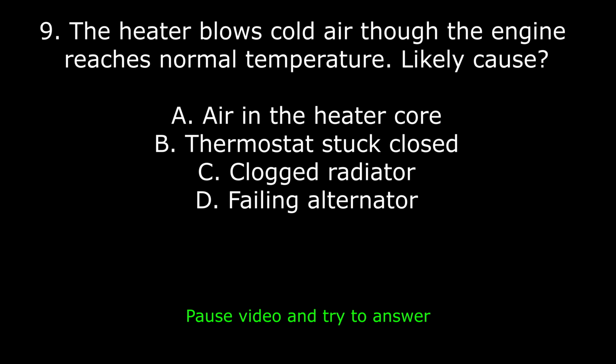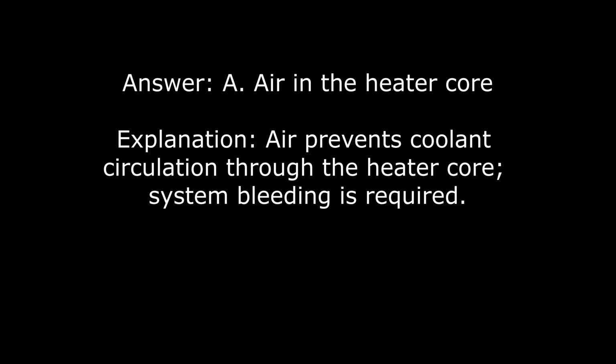9. The heater blows cold air though the engine reaches normal temperature. Likely cause: A. Air in the heater core. B. Thermostat stuck closed. C. Clogged radiator. D. Failing alternator. Answer: A. Air in the heater core. Explanation: air prevents coolant circulation through the heater core. System bleeding is required.